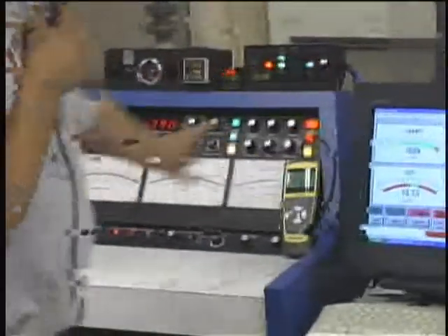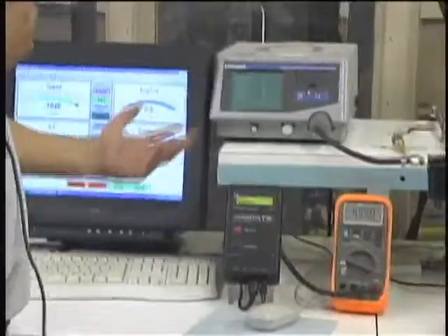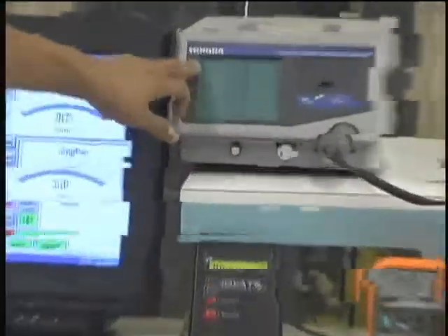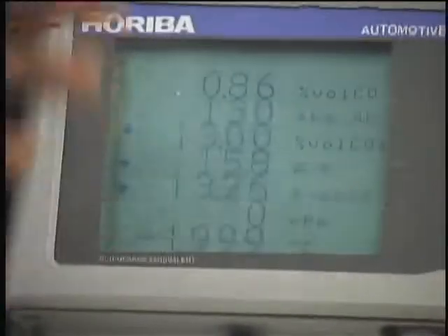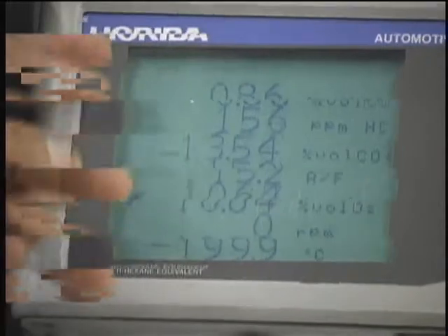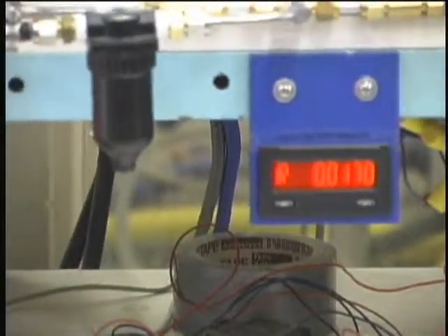Okay, so if we were ready to take the sample, you would open this, close this, open that. Now you're ready to start sampling. If you could zoom in right here, question marks are okay. Arrows, you wait till they disappear. That means the machine's not stable yet. Now that you see the arrows have disappeared, you can start taking the data. So you can start here, take these two, and then, oh, I forgot, this one, you have your fuel turbine flow meter. It's in gallons per minute. You would write that number too. So you could start with this, that, and that.